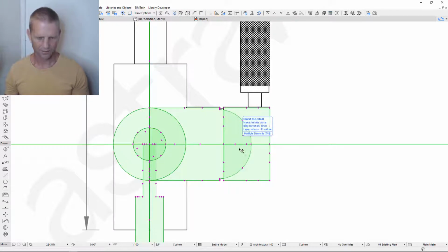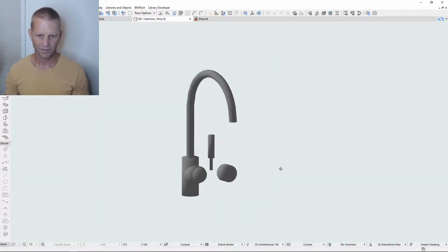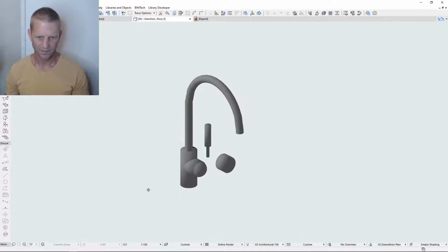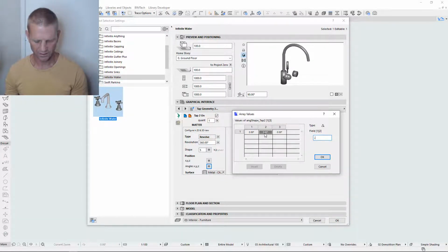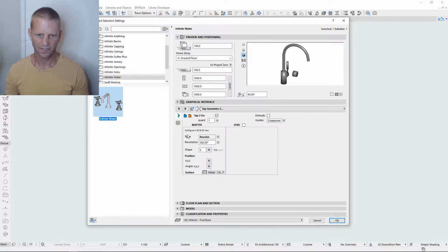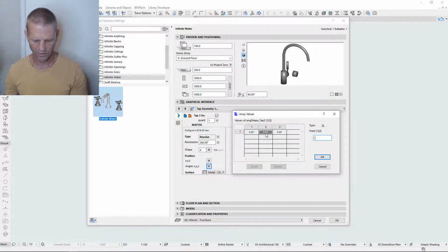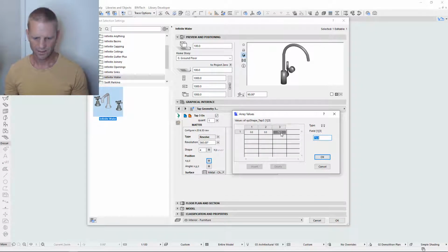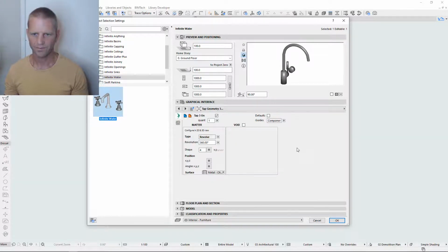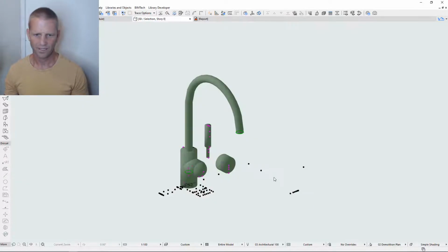Okay, now we have a look at that. See, they're positioned a little bit incorrectly. Go into the settings. This needs to be back at the -90. Click OK, and go to item 3. It should also be on the same logic, -90, and everything is 0. Click OK.